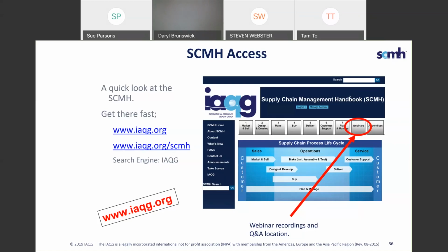We were pouring two materials together, and the ratio of those two materials got out of whack because the bolt loosened up. So you have to take it to the detail that helps give you the information you're after. And again, let the product speak to you. If you've done a PFMEA and you think you got everything attacked, but you still have returns from the field, you still have rejects in your bucket, you're not deep enough. Okay.